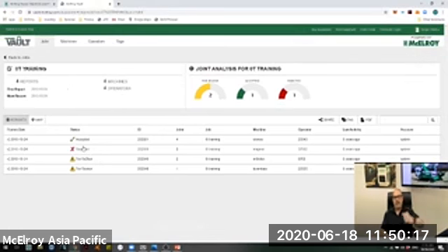Typically, out of 20 welds, it'll show 19 good ones and 1 to review. So if you have a slight spike on the pressure graph and you think that's okay, sometimes it gets spikes when opening and closing the machine, little things like that, you can go ahead and accept it or reject it. That's, as I said, a very cool feature that makes it easy to look at all this information.